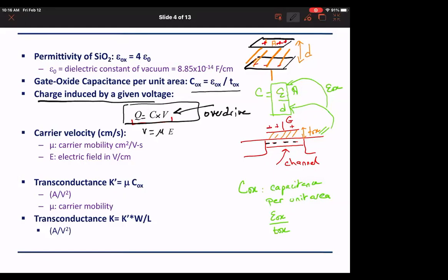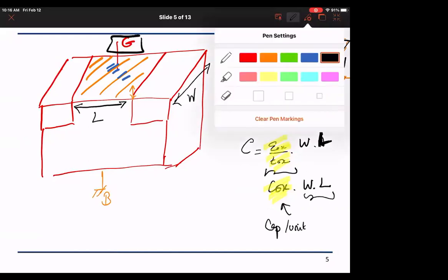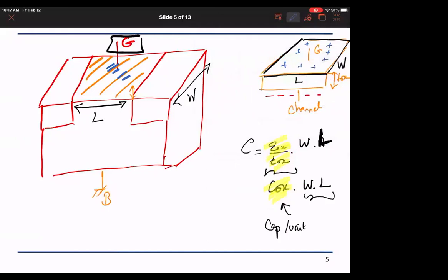Now, from a different angle, this charge that is created by how much Vg is greater than Vt is going to move in my transistor if this is the source and this is the drain. The force that moves those electrons in this direction is due to the electric field created by the drain through the source.